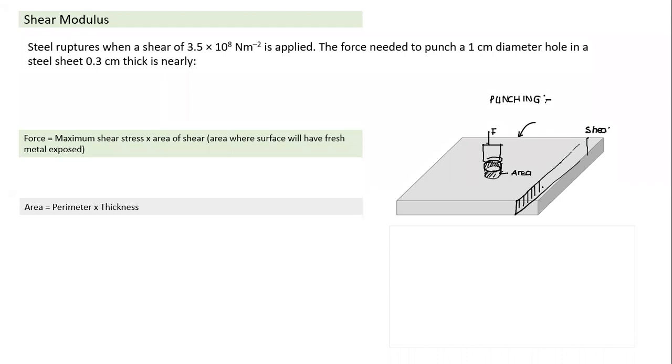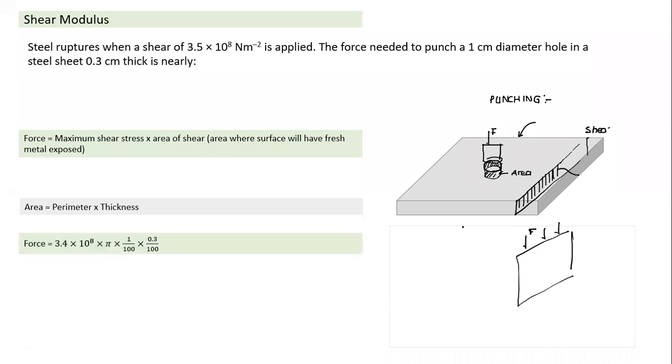The force which needs to be applied by a shearing machine, and a shearing machine could also be a vertical plate, a sharp vertical blade kind of plate. We bring it on top of this metal plate and apply a large force, and it will shear through. Like a guillotine, the word which is used here. And what will the shear area be? Width of the plate into height. And shear strength multiplied by the area is the force needed to shear off one piece of metal plate.